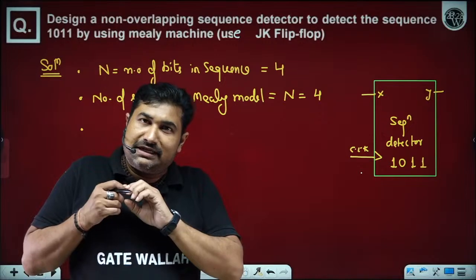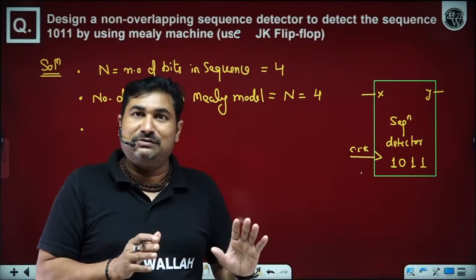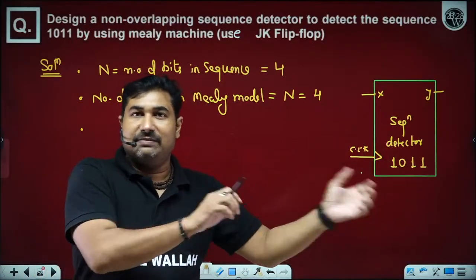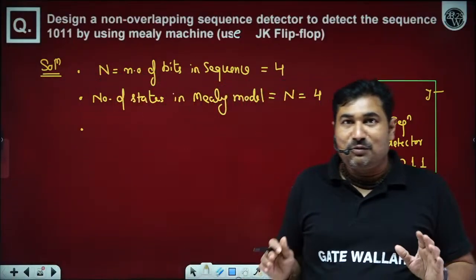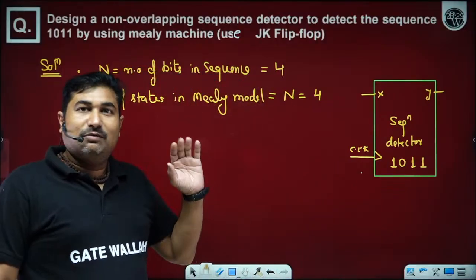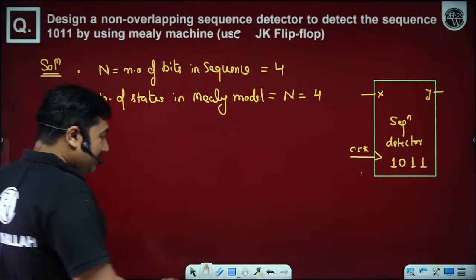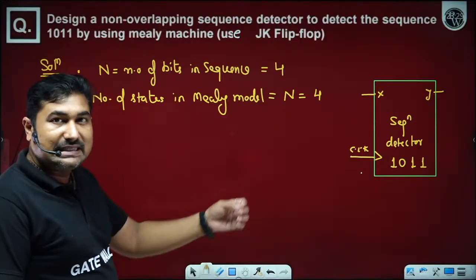So I will send a bit stream with the other inputs as well in the stream. The output becomes high only in a set pattern, and we can decode the message. No one else knows what message we have sent, only the decoder and the sender know. So we are interested in having a 1, 0, 1, 1 sequence detector circuit.